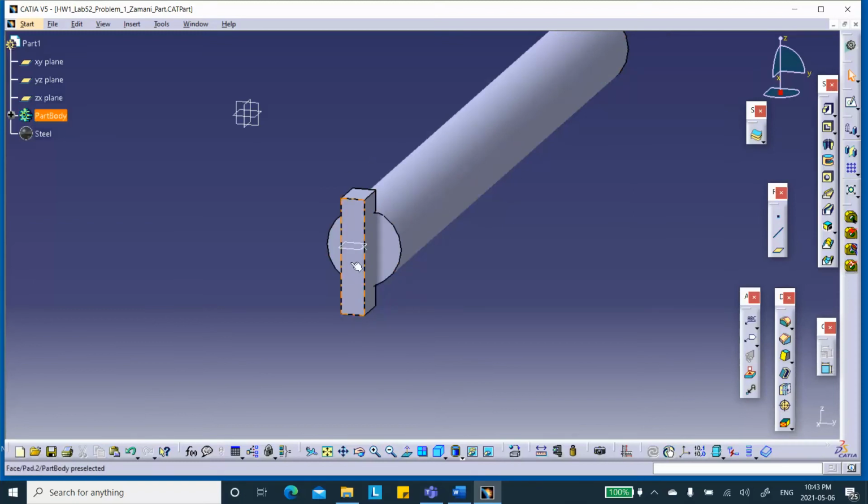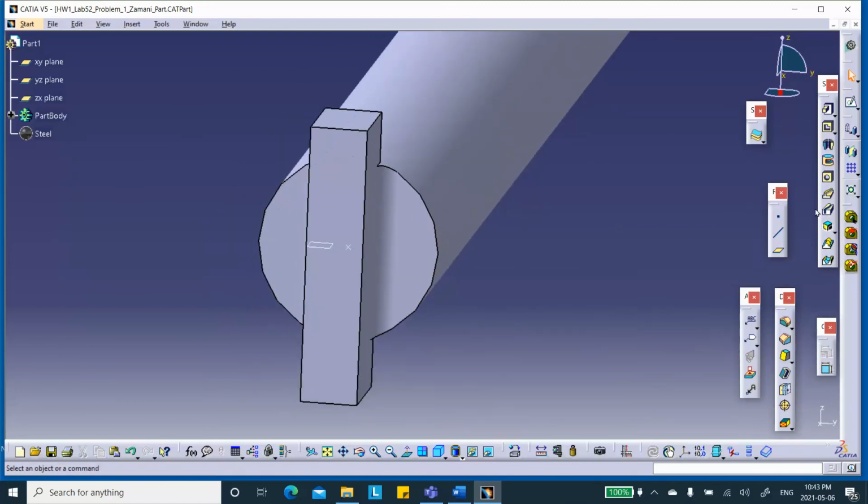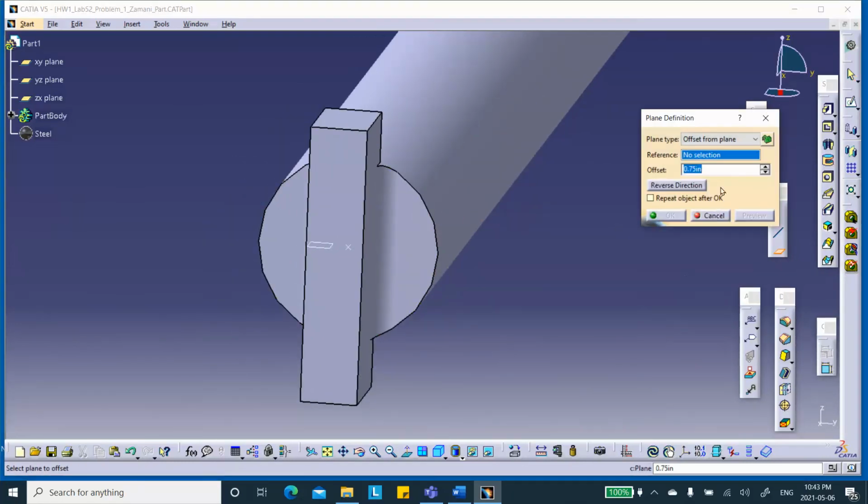And you also want to create a plane in the vertical direction. Now, here's the way I'm going to create the vertical plane. So plane. I'm going to use a different method, let's see now, the different ways of doing it, but the one that I'm going to do is through, how about parallel through a point.